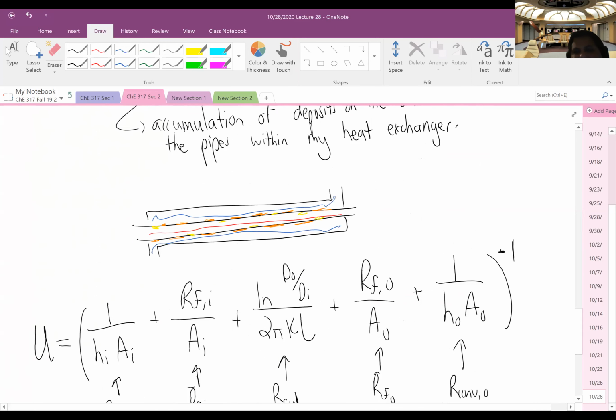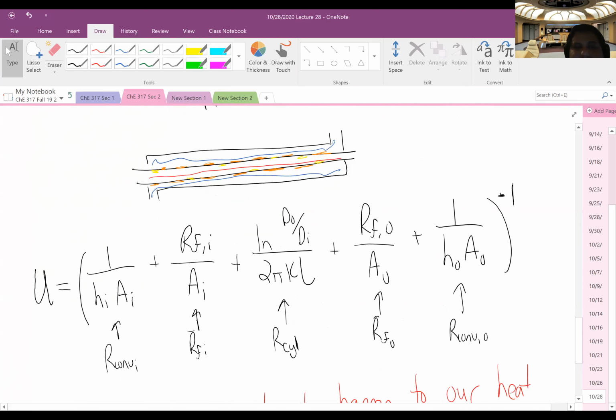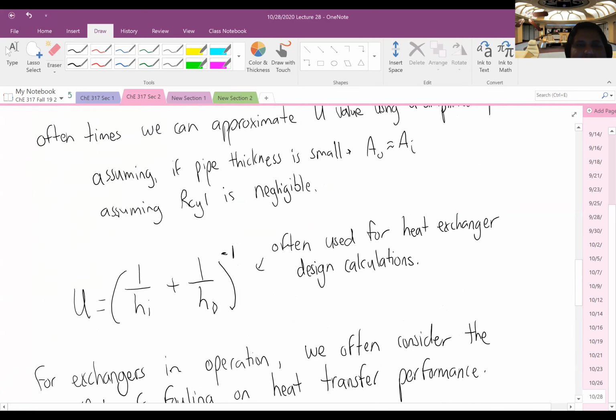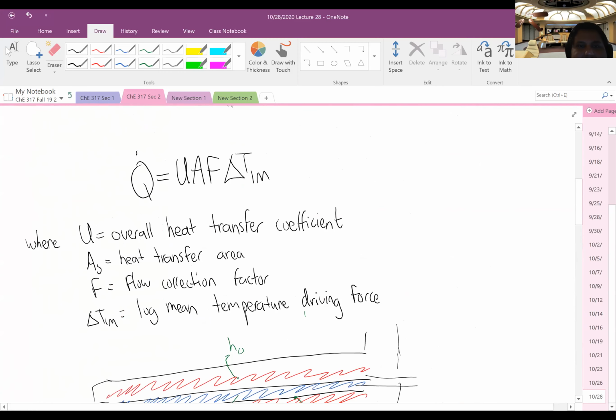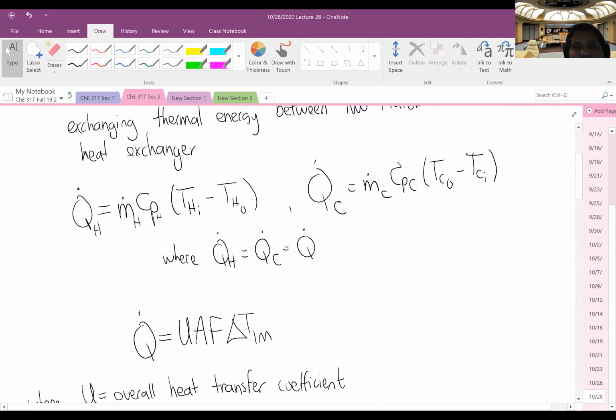There'll be a lesser temperature change for the fluids, right? Based on the design equation, which we have up here, if this Q is smaller, then the delta T on both the hot side and the cold side of the fluid will be smaller, which means the hot side isn't going to cool as much and the cold side isn't going to be heated as much. And so you'll start to see deviations from any desired set points or operating points in your fluid temperatures leaving that heat exchanger.